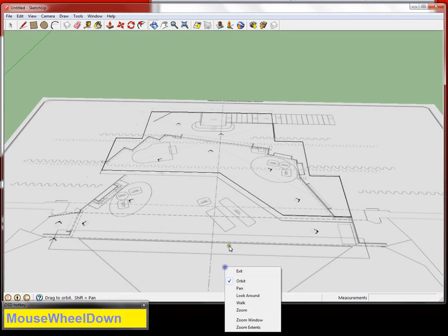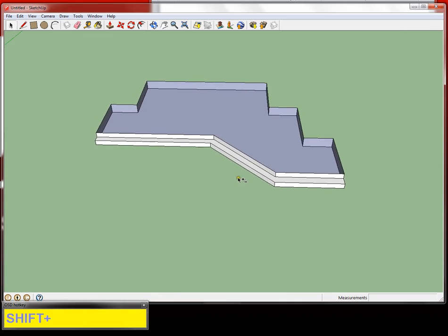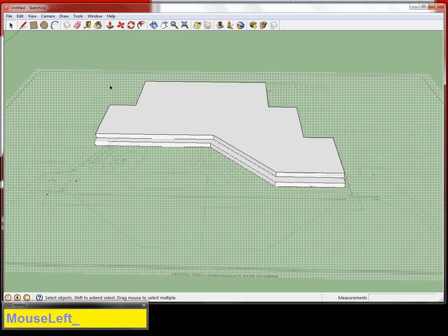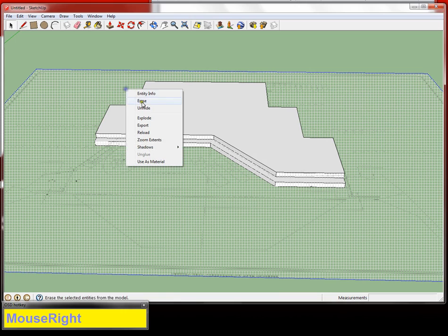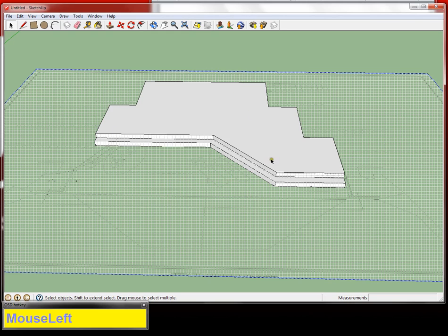And now I'm going to go ahead and hide my floor plan, so you can't see it. So now you can see just my platforms there. I'm going to grab the line tool and cover one of those sides again so that the platform is closed. And what this allows me to do is I can still use view hidden geometry, selection tool, select that hidden thing that I just hid, right click and unhide it. So I can still see that my ground plane is still there and it's still in the exact same place, and I can still use it for reference when I want to put my walls on this platform, but I don't have to worry about it being in the way when I don't want it to. I can go ahead and hide it and then just look at my model.